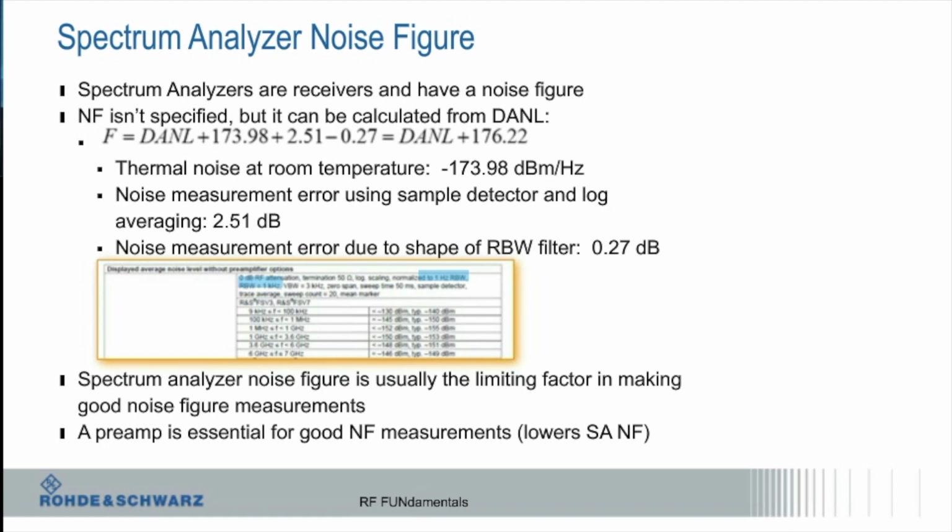A lot depends on, first off, the spectrum analyzer and the settings on it. But typically, to get the lowest noise floor, the first thing you're going to do is disconnect the input, because you don't want to blow it up. Then you go to attenuation and set the attenuation to 0. The default is 10 dB, so you don't blow it up. So that's the first thing you can do.